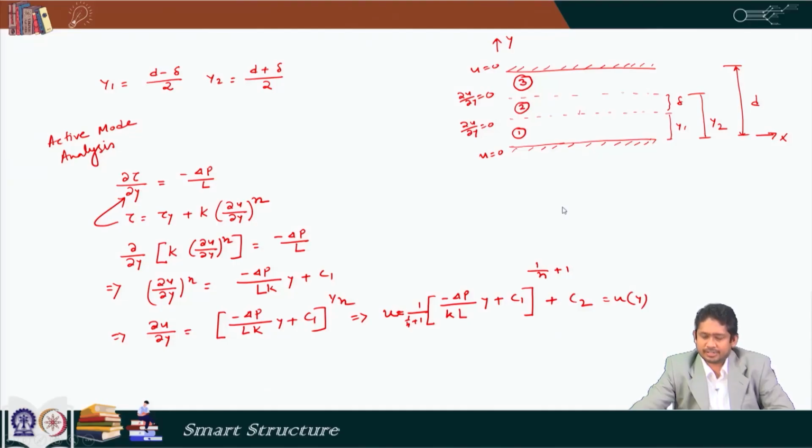Today we will continue our discussion on the flow mode analysis using the Herschel-Bulkley fluid model. We saw that our region has three sub regions, 1, 2 and 3, where the velocity profile is different, and the shear strain variation we saw to be linear, and we found out the velocity distribution over each of these regions 1, 2 and 3.